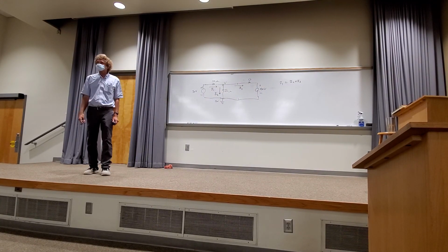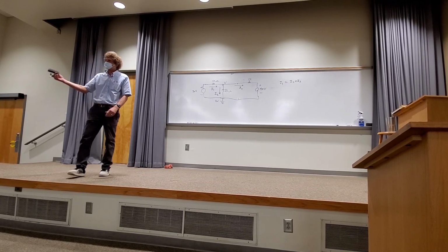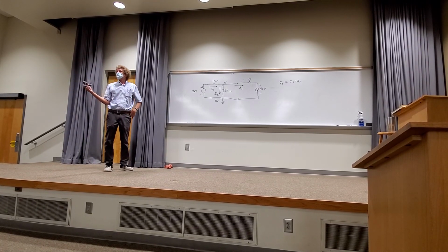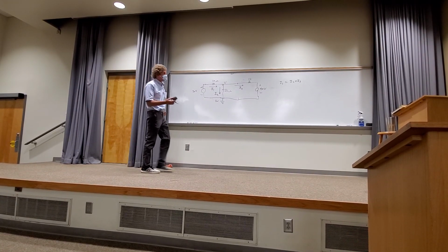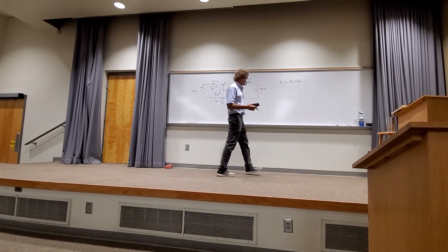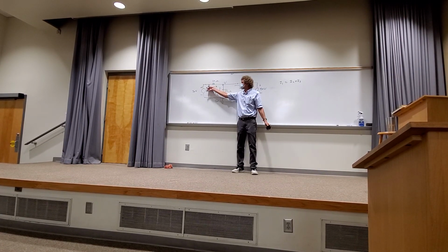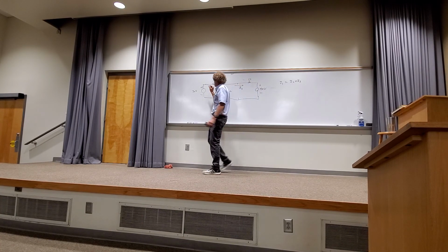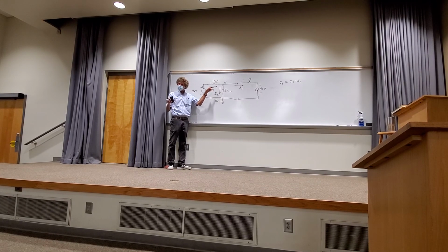Let's write it down. Believe me, this is, I shouldn't say rocket science, because there's arrows in here. You guys are rocket scientists. You agree with me? All right, now how do I get I1? Anyone? Remember what I did? Voltage on the side the current's going into would be plus, minus the voltage on the side the current's leaving, divided by 10, right?